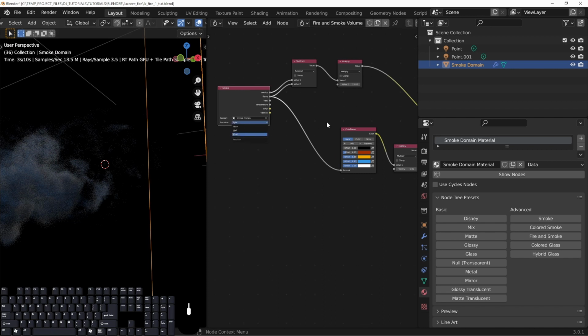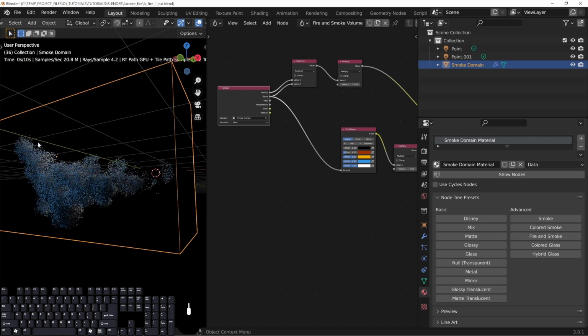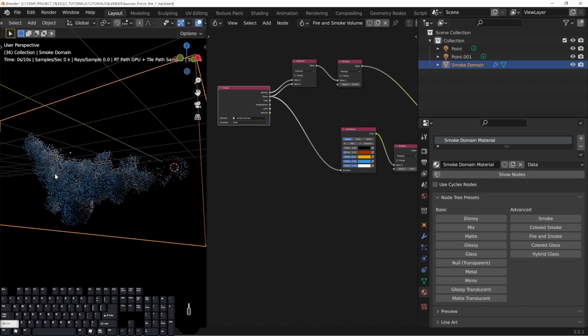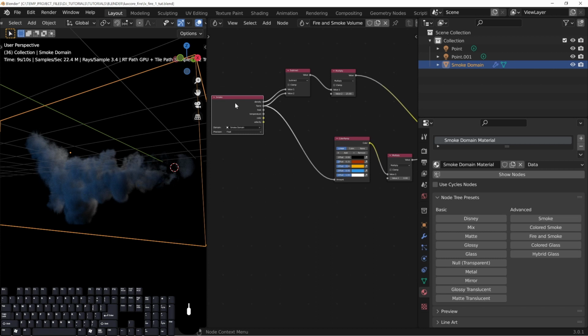Now that we've started to take this information and multiply it against each other and everything else, especially once we add back in the noise to see the really detailed smoke that's happening here, you will notice that there is quite a bit of a difference when you change this from float to byte and to half. And just so that you know, basically this is just what your computer can handle. If float is way too slow for you, you might need to use byte in order to get this done in a reasonable amount of time. It's really just up to what your computer can handle at this point.